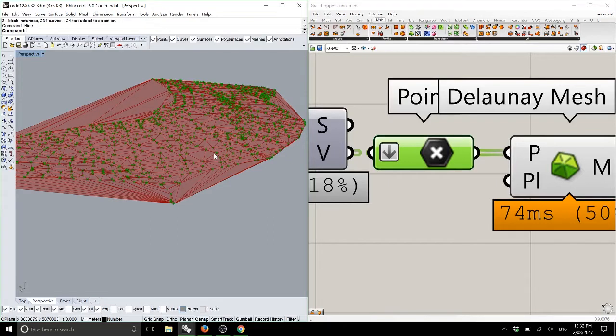So with 2 points, you draw a line between them, and you then draw a perpendicular line at the midpoint. That defines the cell of the Voronoi. So if our other point was here, there's that midpoint perpendicular. How do you know which point to draw to? Which points are a point's neighbor? Because if you have a whole bunch of points in a cloud like this, how does the Voronoi system know that it can't try and create a Voronoi between these 2 points, right? All it uses is the Delaunay system to find out where its neighbors are before it starts doing those cells.